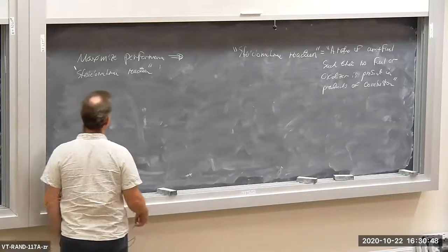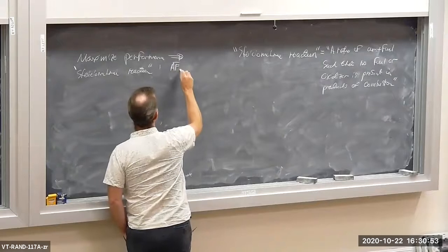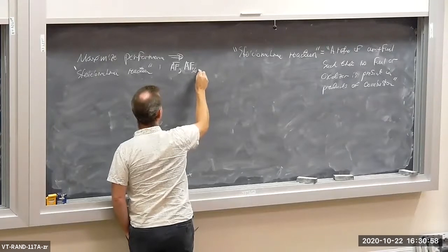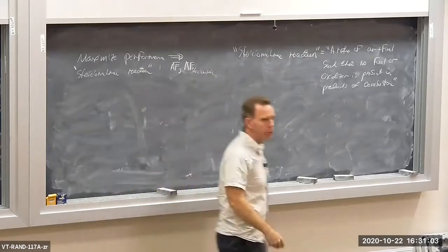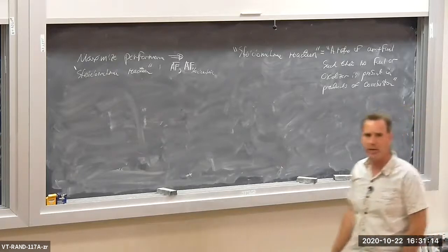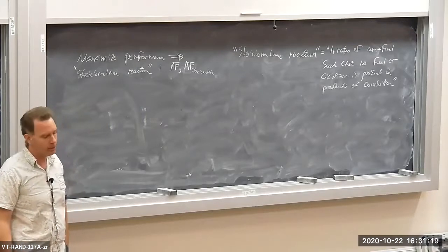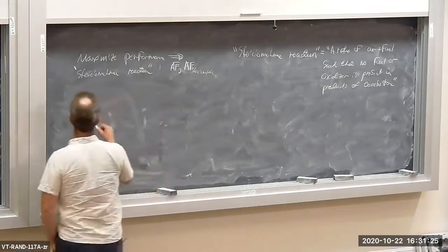So to maximize efficiency, you really want to be operating at a stoichiometric air-fuel ratio to maximize performance. That's basically what you want. Now, sometimes, depending on conditions or depending on constraints or specific desirables, you may want to deviate away from stoichiometric for whatever reason. So in that case, we define what's called theoretic air.